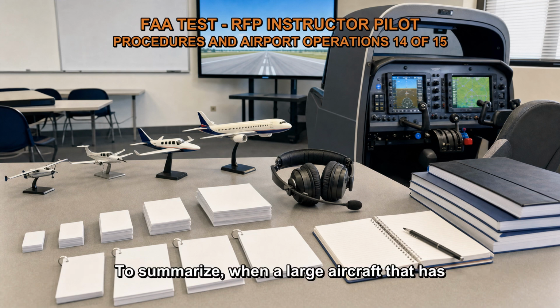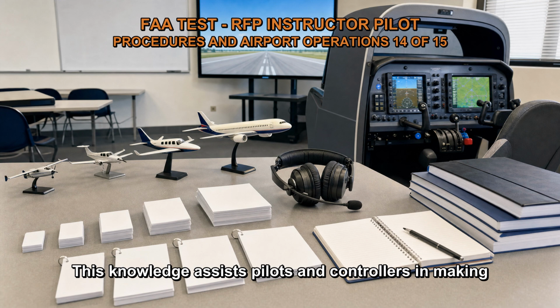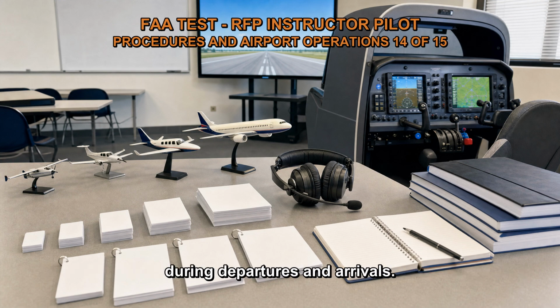To summarize, when a large aircraft that has just taken off experiences a crosswind of 5 knots or less, the upwind vortex will tend to remain on the runway longer than the downwind vortex. This knowledge assists pilots and controllers in making informed decisions regarding aircraft spacing and ensuring safety during departures and arrivals.